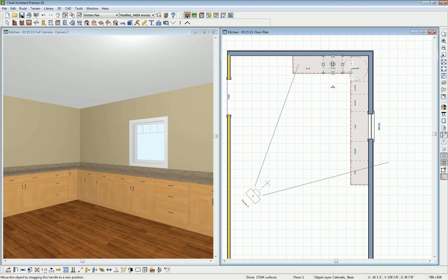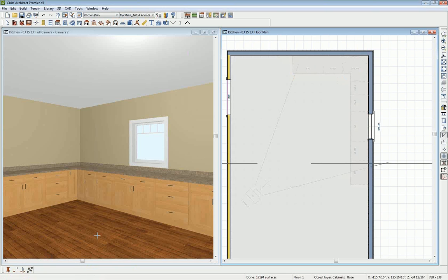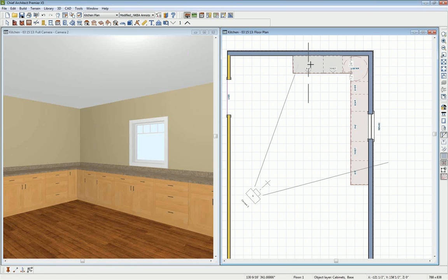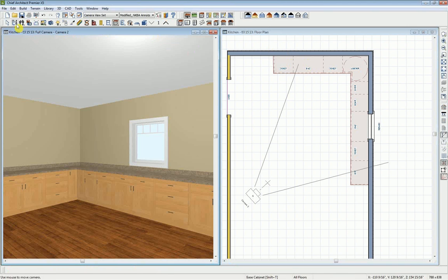We can also single click and in our editing toolbar hit that copy and paste tool, and we have a reflect about object. So with the single click on that, it's kind of like our center object, how it works. Then bring your cursor right over to the 42-inch, single click again, and it just reflects onto the other side. So if you're working in a plan where you need to copy and paste a duplicate, that's very easy to do.